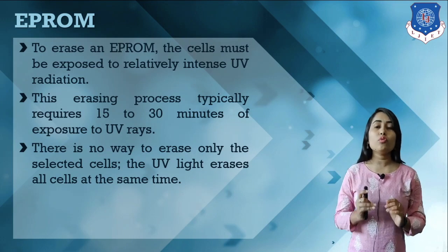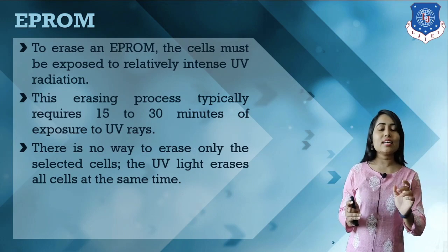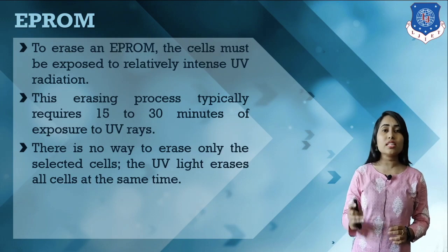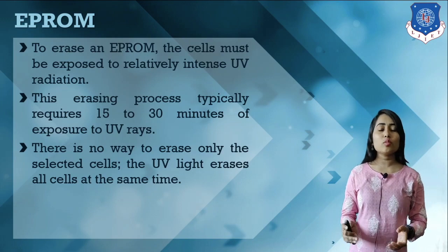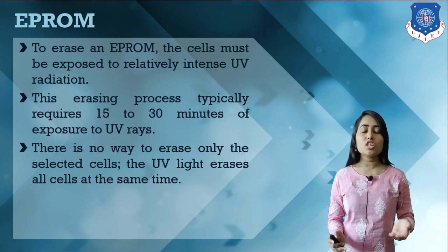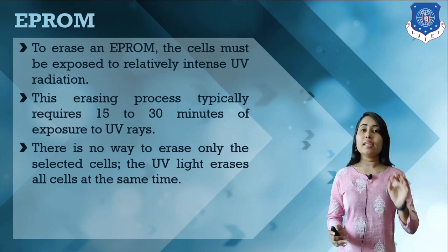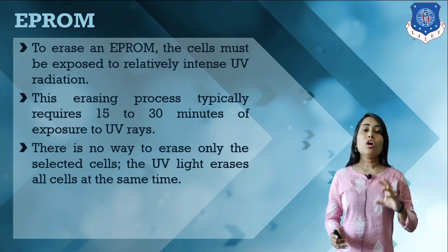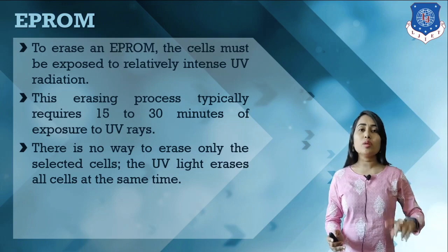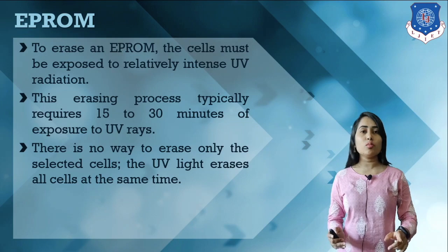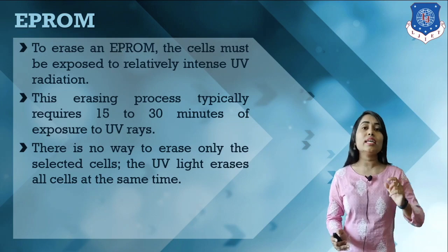There is no way to erase only selected data. We have to erase all the stored data. That means once we apply UV radiation to this memory device, all the data stored in the EPROM is erased, and we can again reprogram them. But there is no way to erase only selected data.